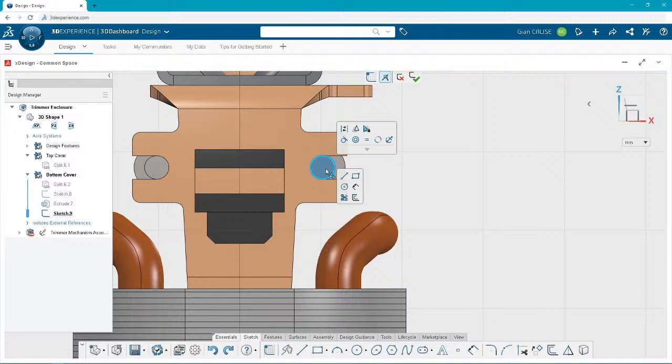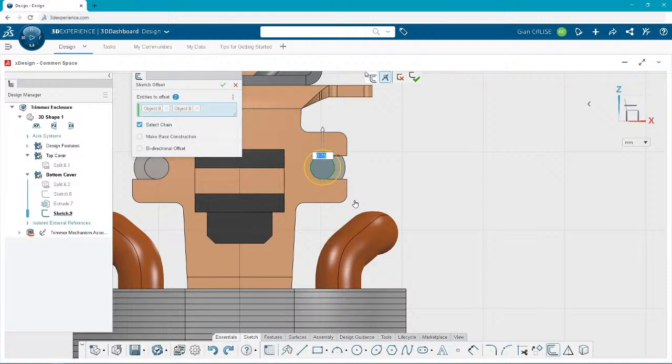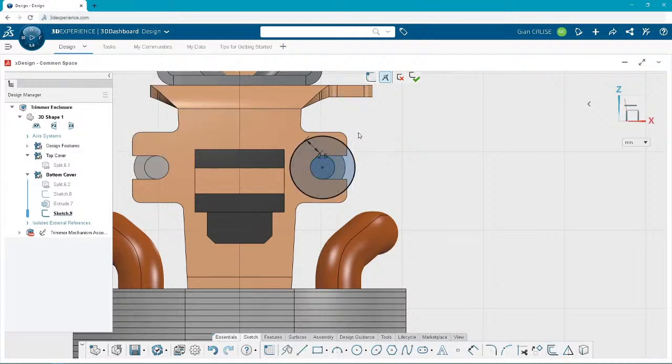And then here's the S key again. The S key is not just for SolidWorks. It's for 3D Creator. It's for 3D Sculptor. It's really anything SolidWorks can get its hands on. You could probably bet that the S key is going to be pretty darn helpful. So in this case, it's giving me a bunch of sketch shortcuts. So I'm going to use the offset. And I could drag that manually, but I think I'll just do 2.5 millimeters. I'll just type that in.